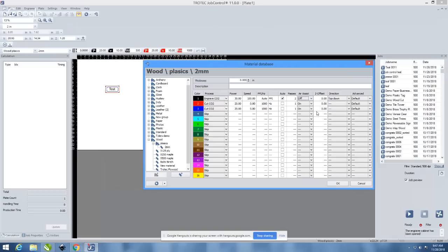John, can you just touch on why it's important to have it on for cut? Yeah, most materials, if you don't have it set to on, well, there's two things. First of all, your material may flame up, so that's certainly the case if you're trying to cut engraving plastic or acrylics or rubber. The second thing that's important too is to make sure it's on to protect the lens.